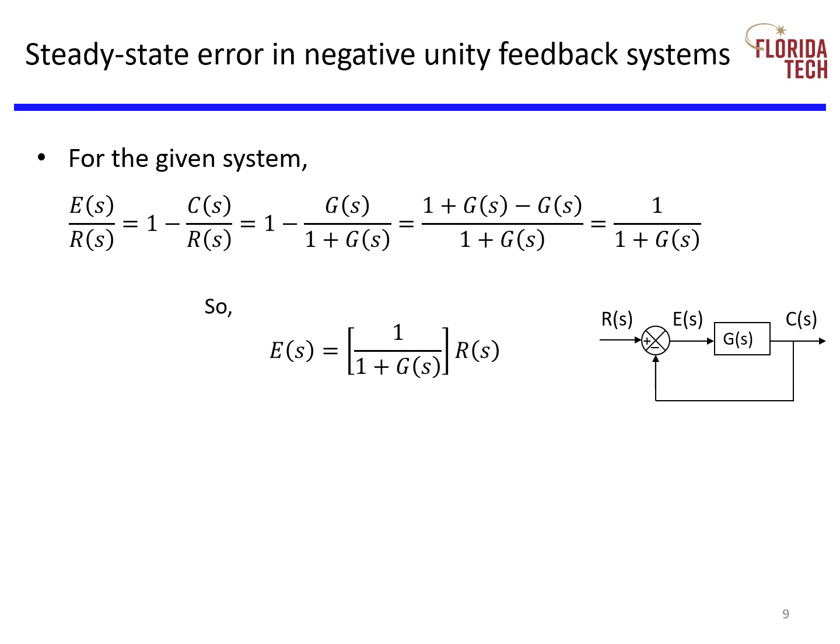Now let's isolate error on the left-hand side by multiplying both sides by the reference input. These math tricks are common. We start by dividing both sides by something, do some manipulation, and then multiply both sides by the thing you divided by earlier. So the error is 1 over 1 plus G in the square brackets multiplied by the reference input.